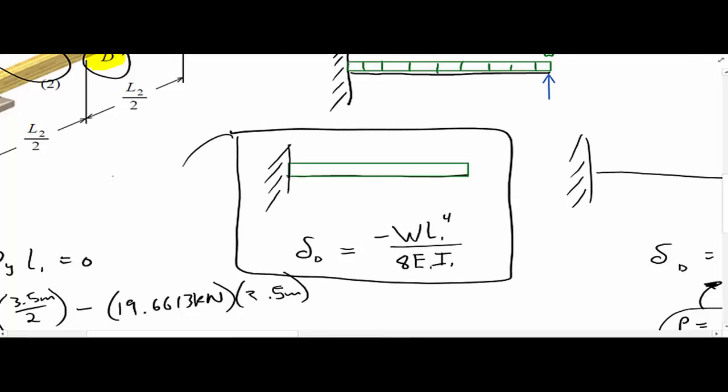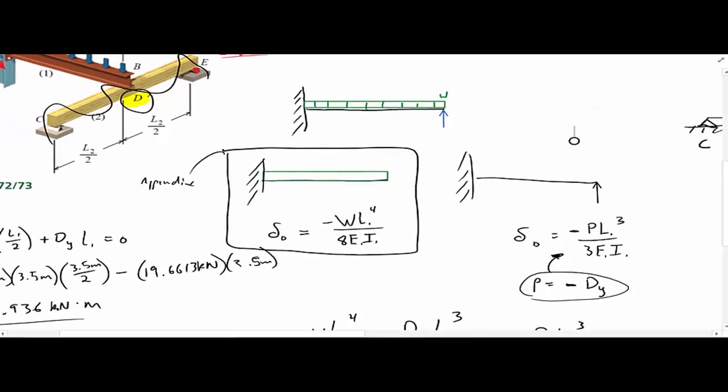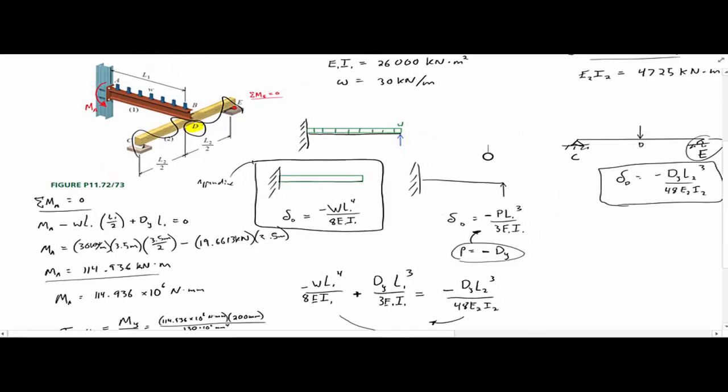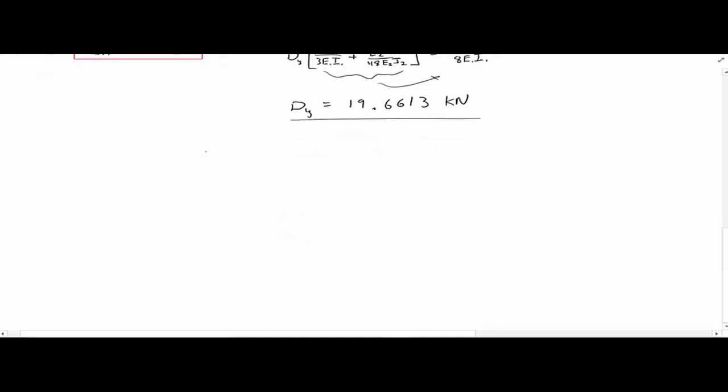So if you look in the appendix, or your handout, you can find the maximum moment. We determined that's going to be at the support. We know what our deflection is. So now we can actually find what the bending stress is going to be, okay? So our maximum moment, I apologize, the maximum moment that we found earlier was with the support in there. So the same place where the appendix is, where we got this information, we can find what the maximum moment is.